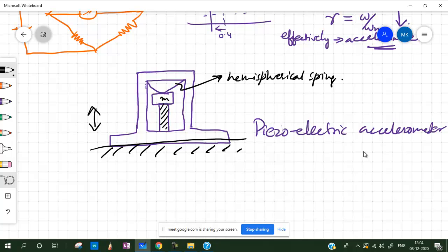For example, in the seismic ones where we have low frequencies, there are issues. Generally the charge in a piezoelectric, as we have seen, when we push it statically, a charge will come out, but that will leak away, it will not stay. So it has to be dynamic in nature, that means moving. But generally piezoelectrics are preferred when we have high frequency measurements.